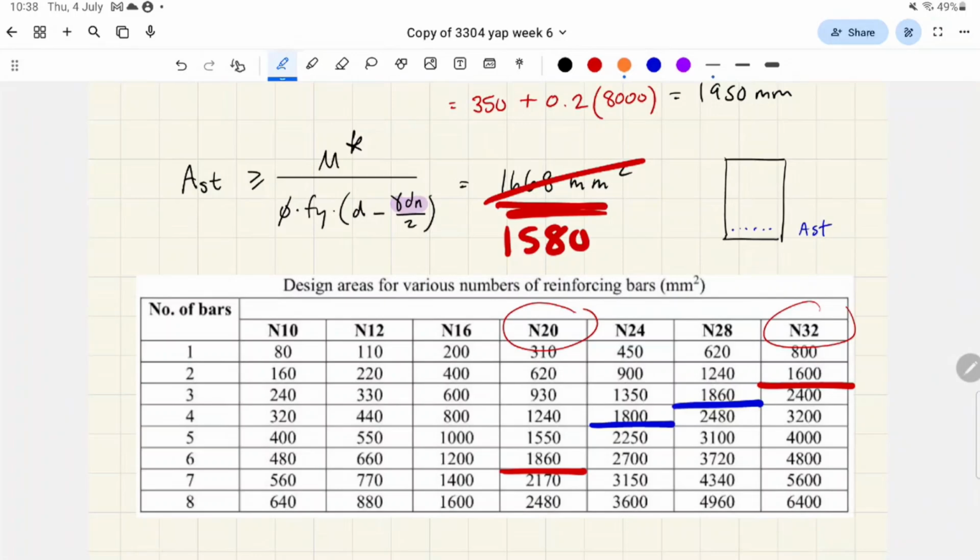Oh, yeah. From a construction, a tradie standpoint, being a foreman for over 20 years, when you pour the concrete, is it just the gaps in between, and then the aggregate will segregate? Perfect. We call that congestion. So if the bars are too close together, exactly right, the spacing between the bars is smaller. And there's spacing requirements so that the aggregate in the concrete can effectively flow through it.